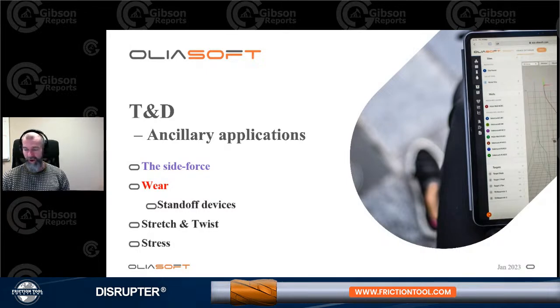Because you cannot wear the walls of the casings more than what the casing analysis tells you is the maximum. The ones responsible for the casing strength calculations will tell you what the minimum wall thickness can be to maintain the integrity of the well.